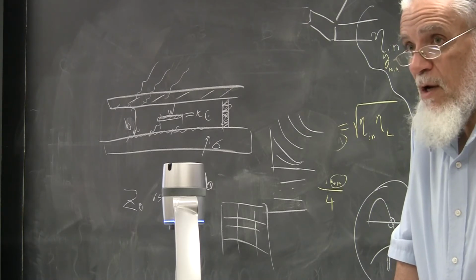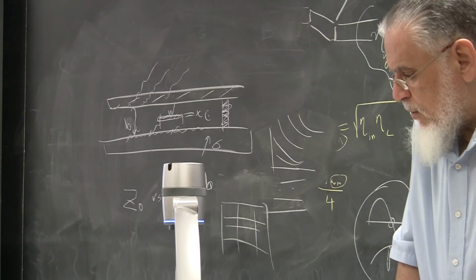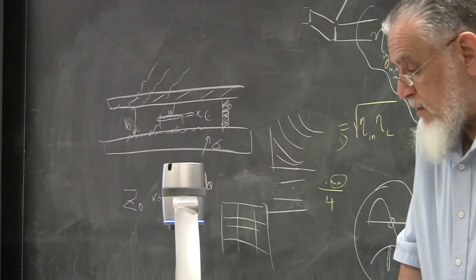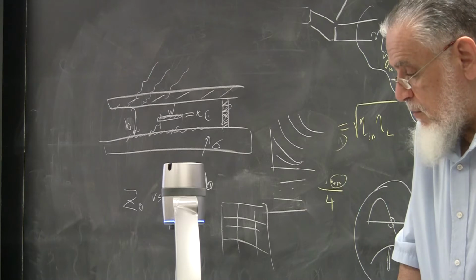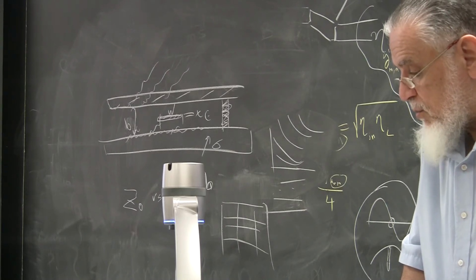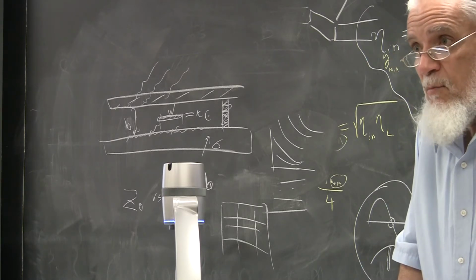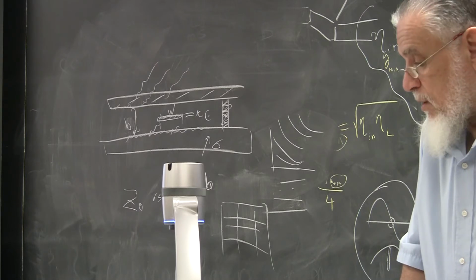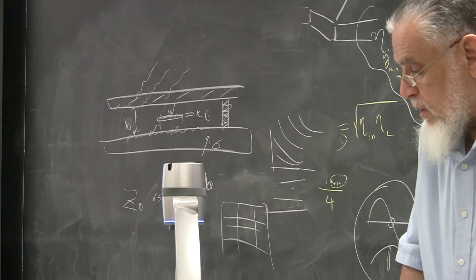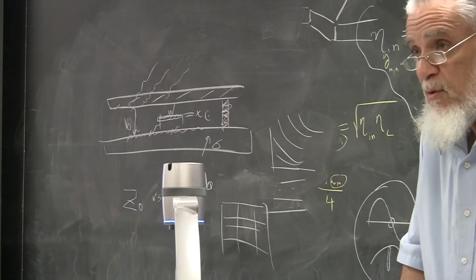You can't take an empirical equation and say, well, that doesn't work out. Where are the ohms? There's no ohms here. You have square root of epsilon r in the numerator, that's dimensionless. And you have B over W, that's dimensionless. Everything is dimensionless, so the right-hand side is actually a number that doesn't have a unit. Well, the left-hand side is ohms. Right? But that's how empirical equations work. They don't necessarily work with units. So you put the numbers on the right-hand side, and you get a characteristic impedance number on the left-hand side, and that's about it.